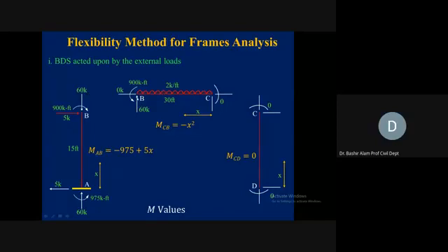60 at B was upward, so here 60 in the downward, so the joint is in equilibrium with respect to the vertical loads. Horizontal is 0, so 0 is transferred here. 900 is counterclockwise, so 900 clockwise now. This joint B, the equilibrium conditions are met.